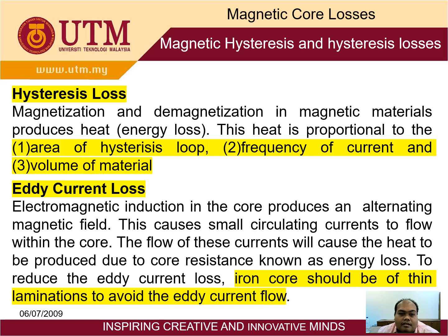So the losses are two: hysteresis loss and eddy current loss. To reduce the eddy current loss, you laminate the core.